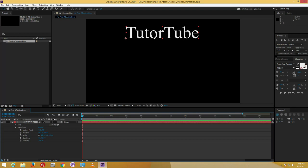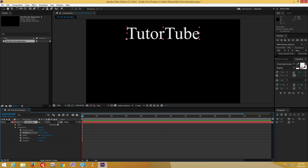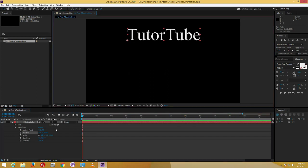options. Now, since dragging this from top to bottom is dragging the position, I'm going to have a keyframe on the position right here. So this is my starting frame, and I want this text to be here at the end of 2 seconds. So I'm going to have my title over here. I'm going to click this little stopwatch icon before the position.